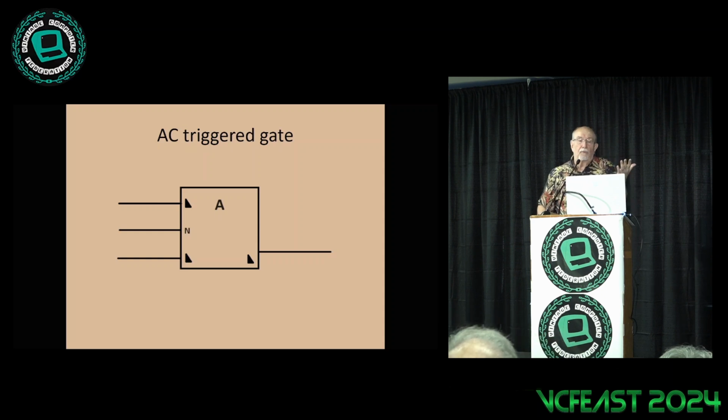To give you an example of why this would be handy: you have a disk drive and you're writing to it, and you want to know if while you're writing you hit a sector mark. Well, that means you've overrun, you've got an error. Well, you just make write one of the arming signals, and the sector mark is the edge trigger. If it edge triggers, a pulse goes out, turns on an error flip-flop, and you've detected the error.